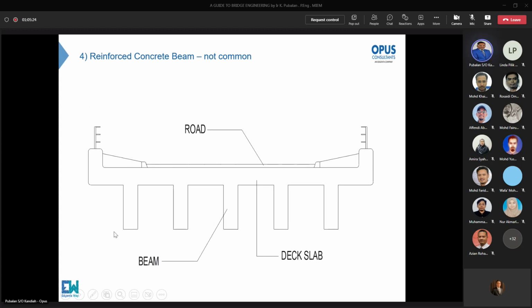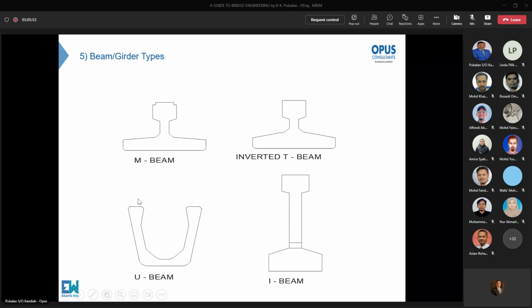But the beam below may not be able to take the forces arising from the additional load. So you have that situation. This normally has to be done during the design stage itself. That's the problem. You can provide a higher parapet, but the beam can break.